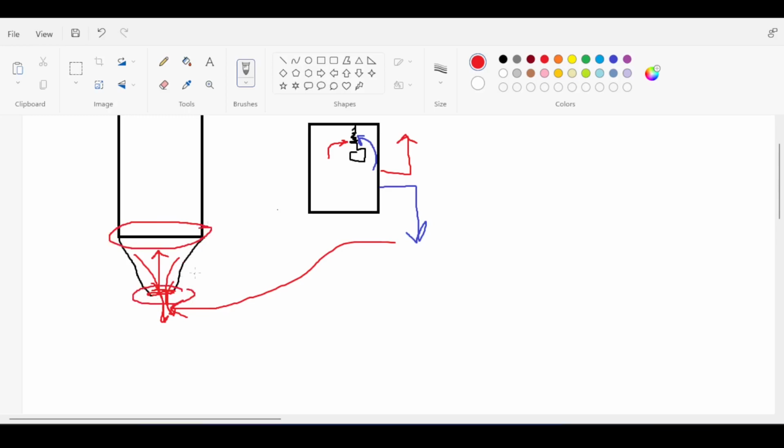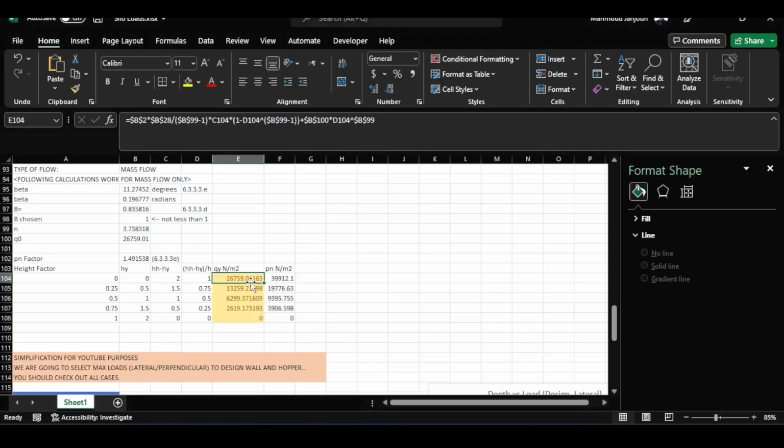So you can calculate this from fluid dynamics, that V multiplied by A equals V multiplied by A, and you can derive an acceleration theory here, that acceleration multiplied by A for one side equals acceleration multiplied by A for the other side. What I'm trying to say is that this will accelerate at 9.81, but this will accelerate at less than 9.81. And the smaller the cross-section becomes, the higher the acceleration, so the higher the weightlessness feeling. And this is why you see a very strange phenomenon, that in the beginning here you feel the full weight, and in the end here you feel weightlessness.